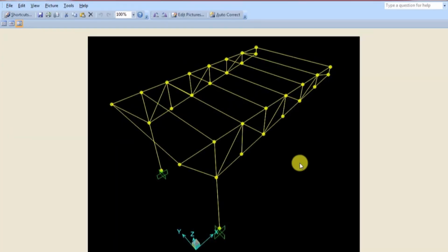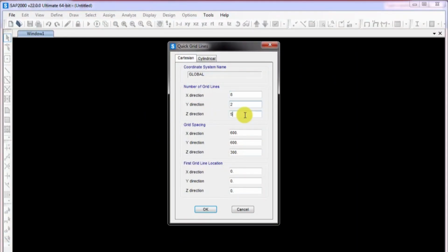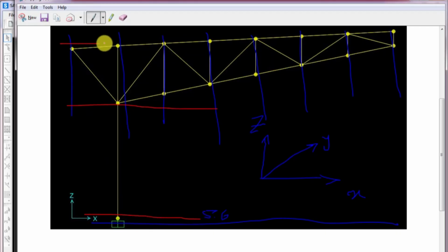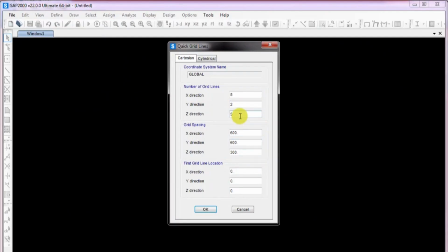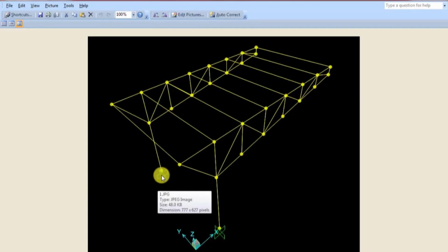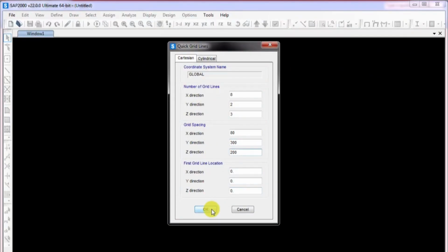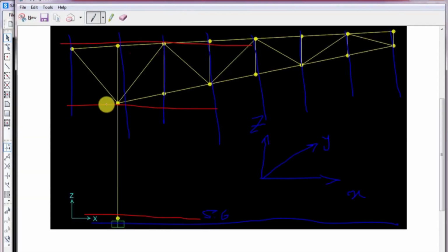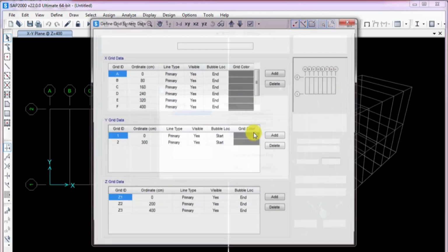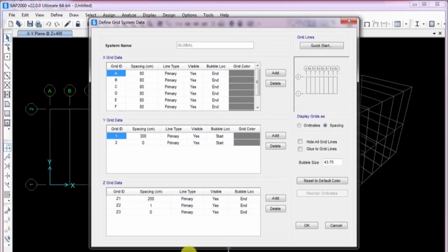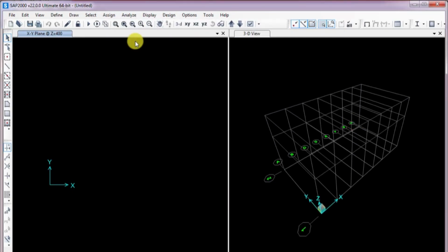The span of the structure is taken as 3 meters and the length is 5.6 meters. To form the truss geometry, the length is divided into 0.8 meter segments, resulting in 7 equal bays. Now, let's move into SAP and start building the model from scratch. Click on New Model. Before anything else, make sure to set the working units to kilogram/centimeter. Next, select the grid-only option so we can manually define the geometry of the structure.